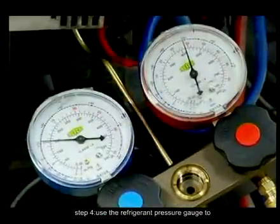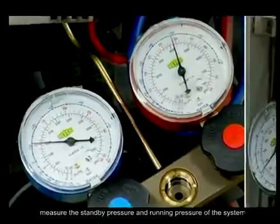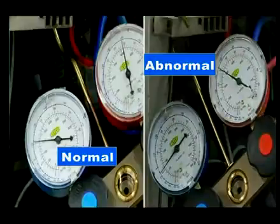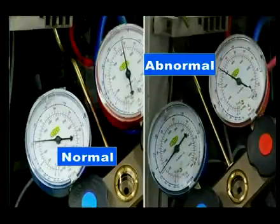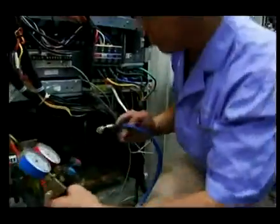Step 4. Use the refrigerant pressure gauge to measure the standby pressure and running pressure of the system. Compare with the other normal machines right there to judge if too much additional refrigerant has been charged to the system. Check if there is air or nitrogen mixed in the system.